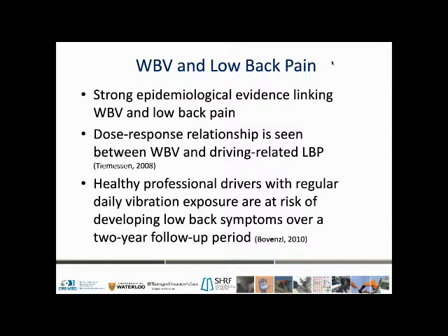Secondly, whole body vibration reduces the amount of nutrients delivered to the spine. For one, vibration increases the amount of muscle activity needed to stabilize the body, and this constricts blood vessels needed to deliver nutrients to the spine. Also, the prolonged sitting that's often associated with operating heavy machinery compresses the discs and pushes the nutrients out of the discs. And this reduces the ability for the disc to repair. And all this is further aggravated by vibration.